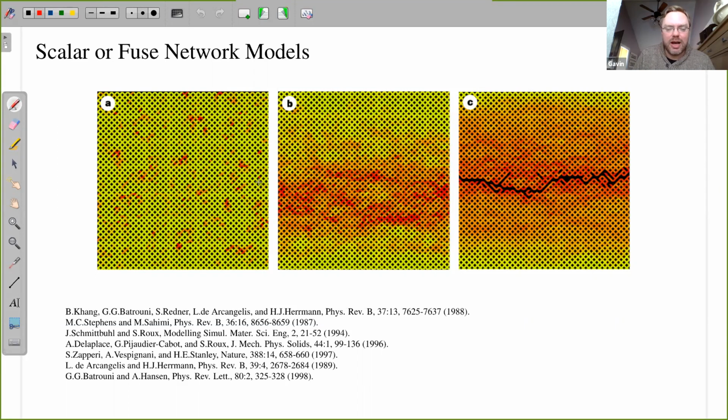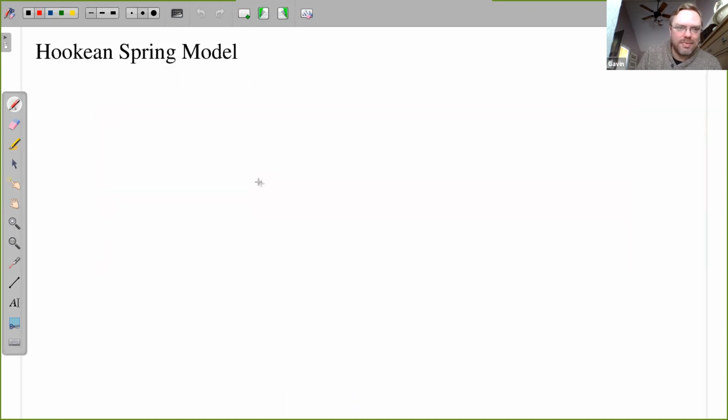And these kinds of techniques are generally used to simulate fracture behavior and trying to probe the patterns of cracks and things. So here's a simulation where the damage accumulated in the material, and ultimately you got fracture along it. And this would be like imagining a network of resistors and having some of those resistors start to burn out. Right, that's the basic type of model.